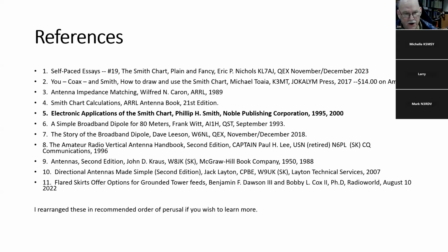And I will share that some of you know I spent a long time in the Navy, and on Navy ships, our transmitting antennas tend to be 2 to 6 megacycles, 6 to 10 megacycles, and 10 to 30 megacycles. So they're pretty broadband, and the antenna tuners that couple a transmitter to that antenna are designed to handle that. And I will tell you that we feed multiple transmitters into a single antenna. Okay, what about receiving? Well, we use separate antennas for receiving, and that's a whole different story.